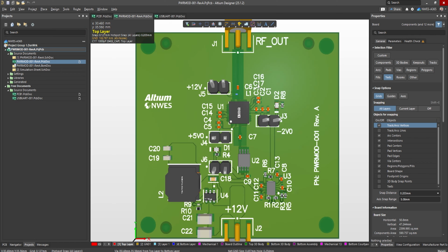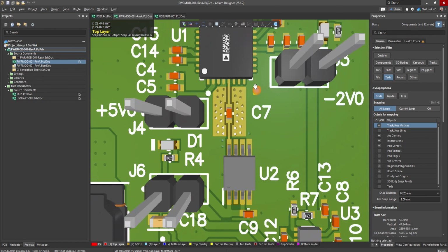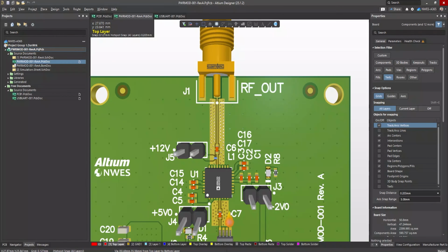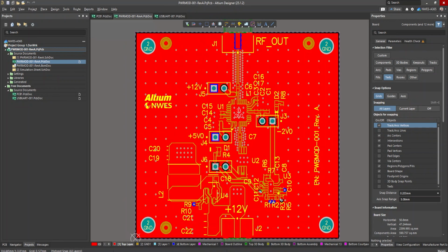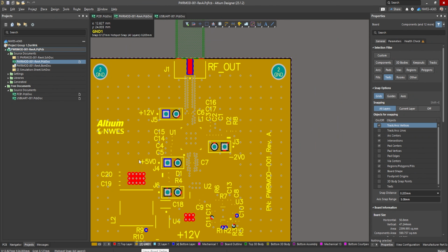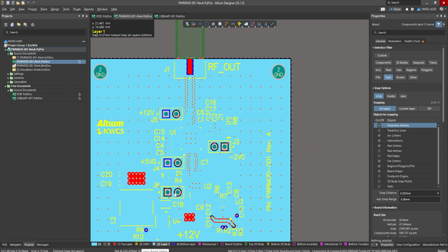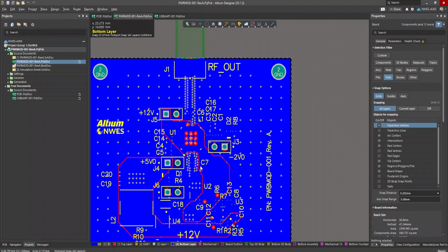This power module, or power amplifier module, uses a coplanar configuration as well, but we already have a ground plane here on layer 2. And then we also have ground here on layer 3, and then we have some additional polygons on layer 4, also with coplanar ground.